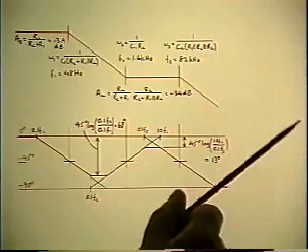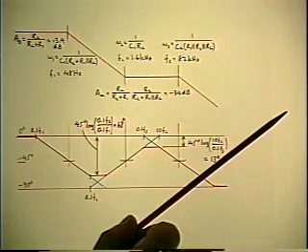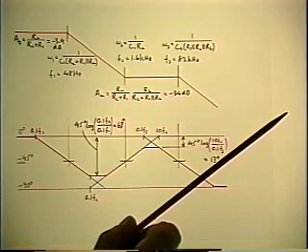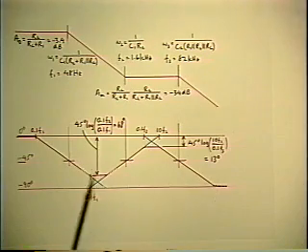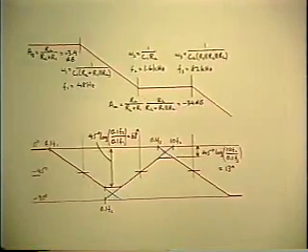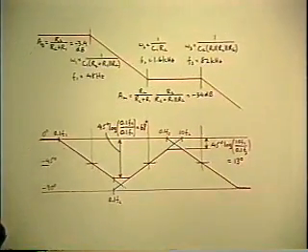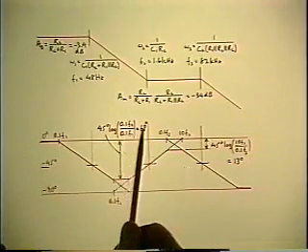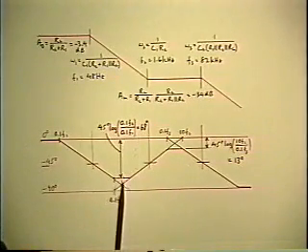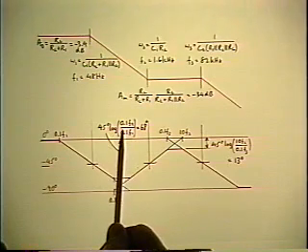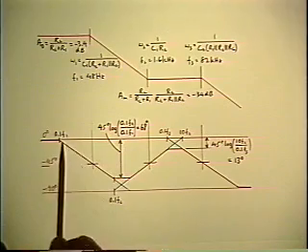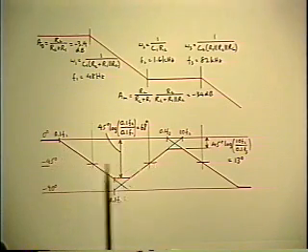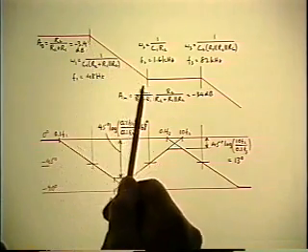Now, up here, you get another phase lead because of the extra resistor. So you simply do the same problem twice now to make both of the maximum phase lags not greater than 50 degrees. And of course, it's easy to do that because you start with a known value of the maximum phase lag, and according to that little handbook formula we had earlier on, you can translate that directly into the required ratio of these two corner frequencies, which is the first pole and the zero.